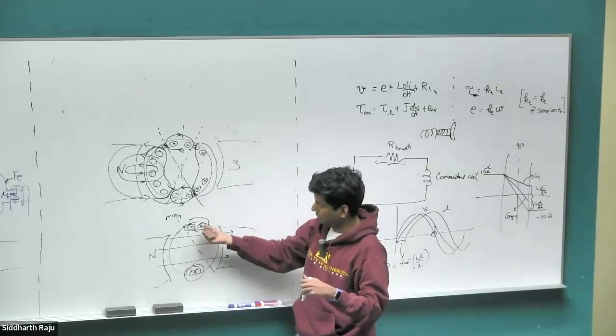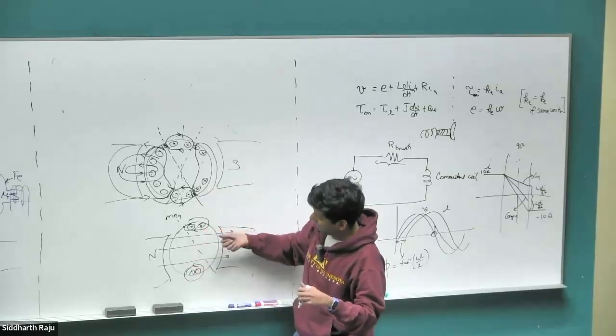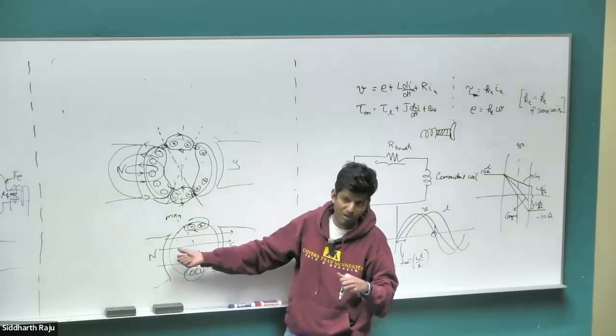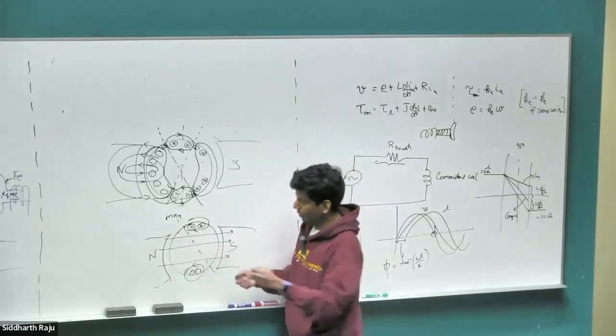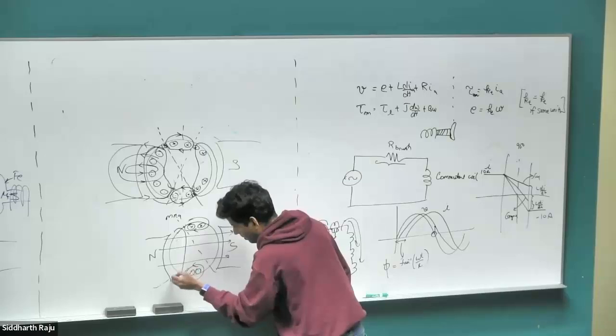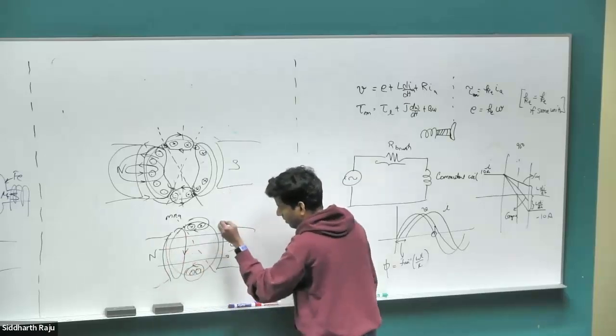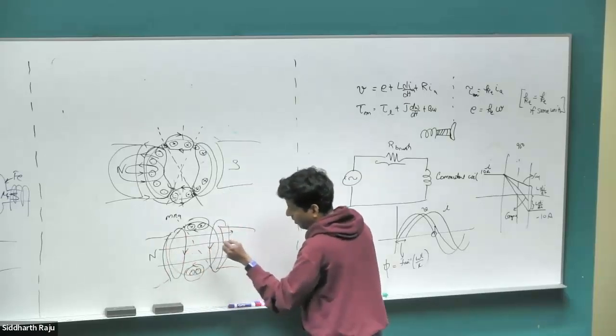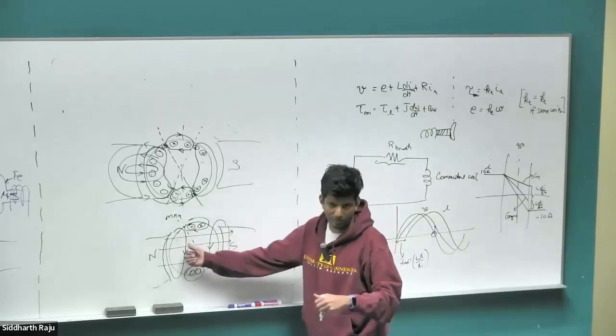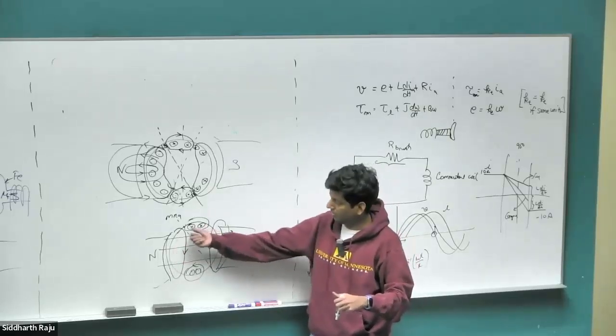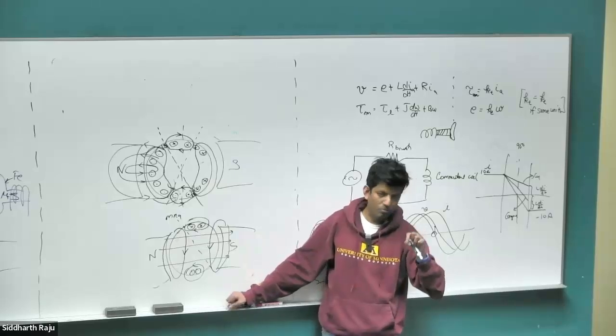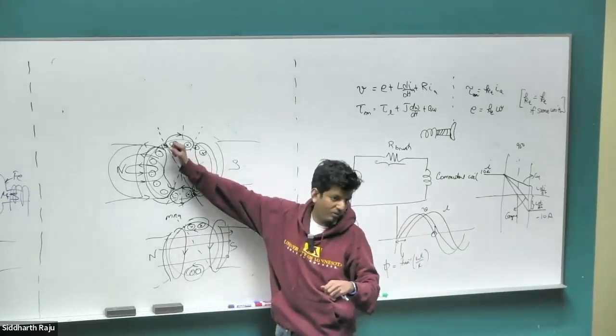Right? In this case, there are two sets of conductors that are actually creating magnetic field going in the opposite direction to the magnetic field due to the magnet. The rest of them would still create the same thing as before, going perpendicularly down, going perpendicularly down. So the other two are still cross-magnetizing fields. These two coils are creating direct magnetization fields because of the misplaced position of our commutator segment.